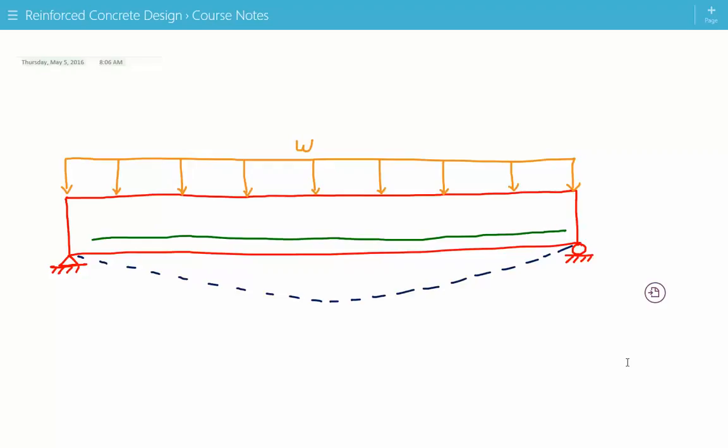see that the top half of the beam is under compression and the bottom half is in tension, and bending is about the neutral axis, which we will show momentarily. To understand the stress and strain occurring on this beam, we have to take a look at a cross-sectional view.